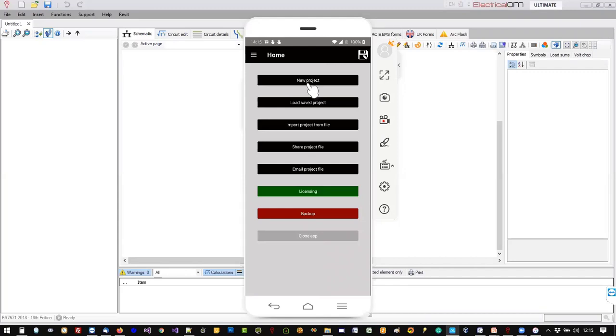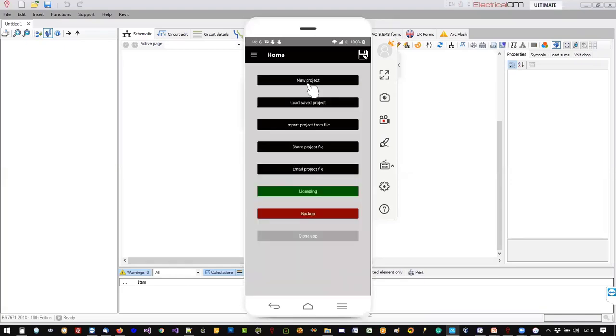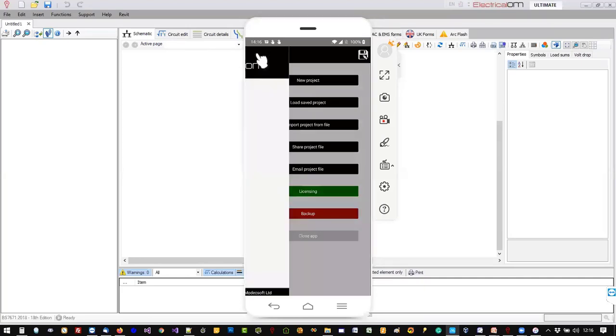Just want to answer one more question. Yes, I have one from Jake. He's also asked, when inserting the electrical build and creating the schematic, will it flag up issues? Yes, if you've selected things like protected devices, manufacturers, makes, and cable sizing, it will flag up warnings in the core software of that data you've collected, where you don't have correct selectivity, issues with adiabatics, or issues with conductor sizes, all the things you would expect to see as you were building a network within the core software. That information will also be checked when it's brought in from the mobile app.